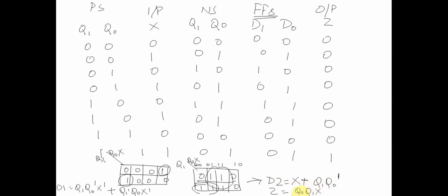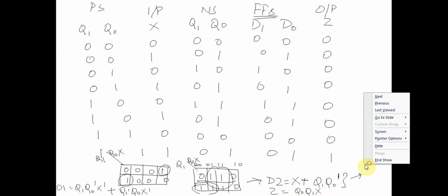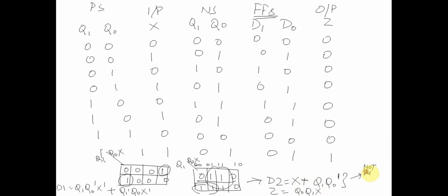Now if we build a circuit using this, what all will we need? My D0 will require NOT and XOR gates. My D1 will require two NOTs, two ANDs and one OR. See the number of gates we end up using over here.